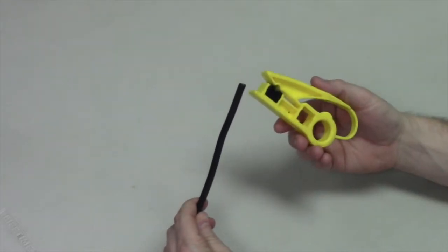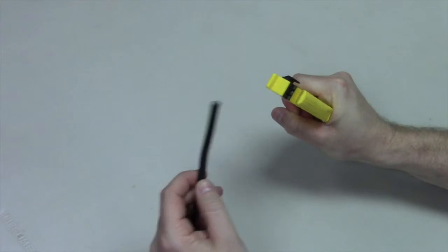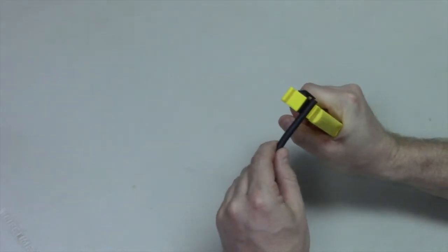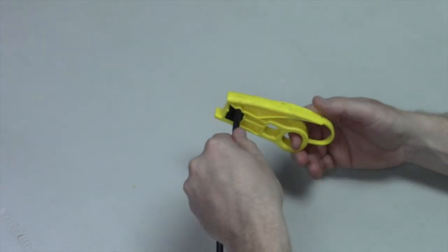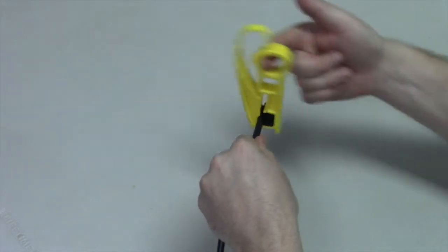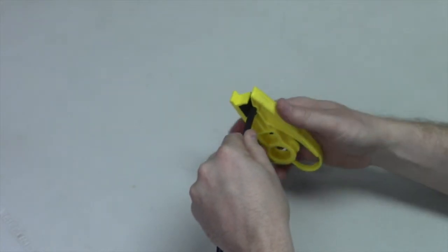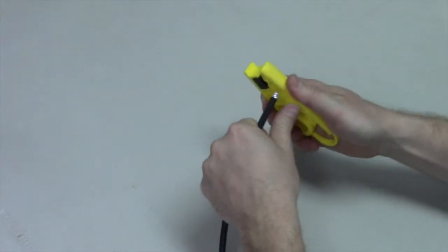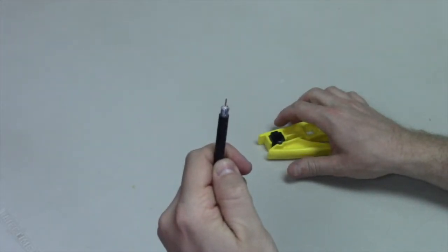The coax strippers have two razor blades inside that score the sheathing. Put the coax cable inside the strippers and spin the strippers around 1 to 5 times. Then pull off the sheath of the cable. As we talked about earlier, within the cable is aluminum shielding. You will need to fray it out around the outside jacket.